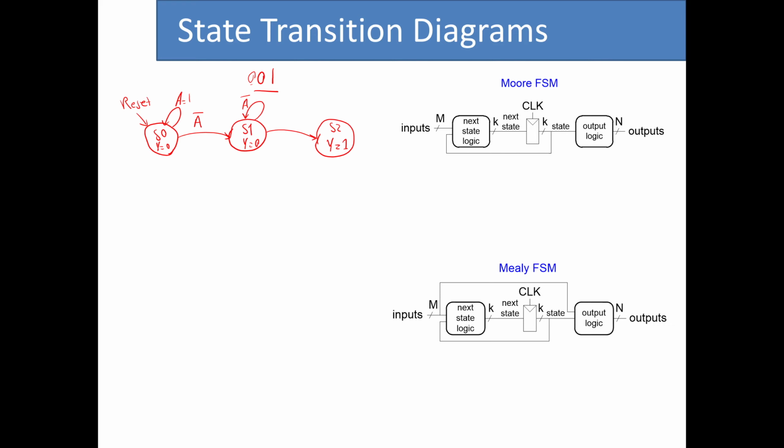So now that we have this, we need to see where we should go after we got to state 2. Because we want to detect all the patterns of 0 followed by 1 in our sequence. So what should we do if we detect a 0? Since if we detect a 0, that is basically half of the pattern, we can go to state 1. On the other hand, if we detect a 1, we need to go to the initial state.